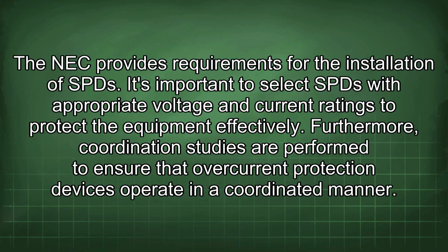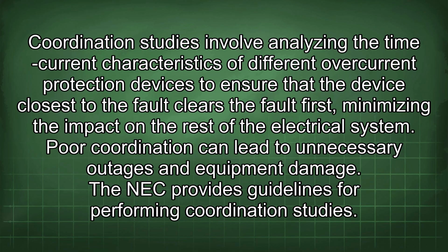Furthermore, coordination studies are performed to ensure that overcurrent protection devices operate in a coordinated manner. Coordination studies involve analyzing the time current characteristics of different overcurrent protection devices to ensure that the device closest to the fault clears the fault first, minimizing the impact on the rest of the electrical system. Poor coordination can lead to unnecessary outages and equipment damage. The NEC provides guidelines for performing coordination studies.